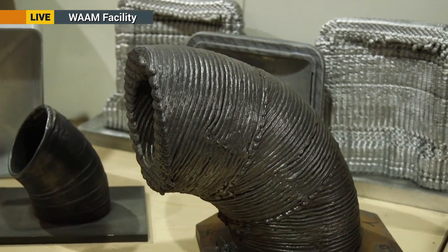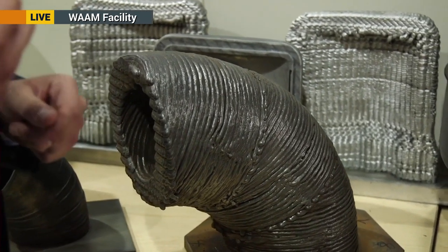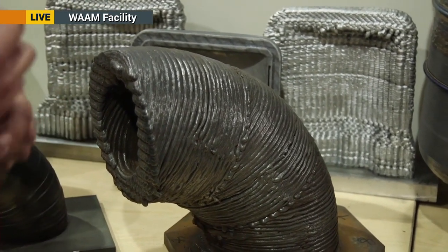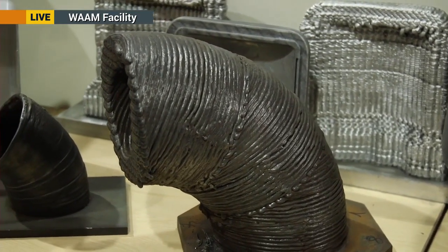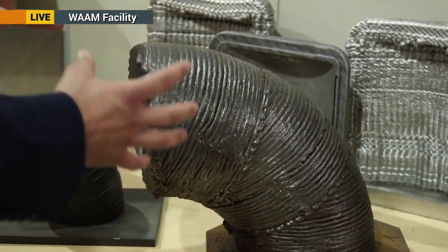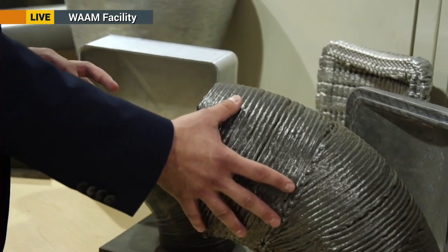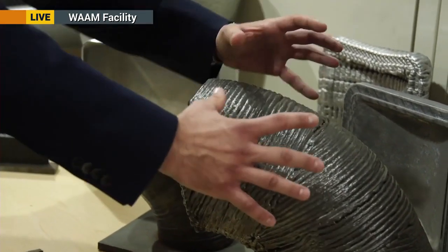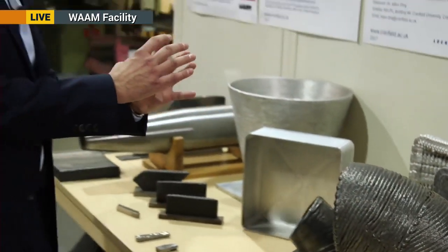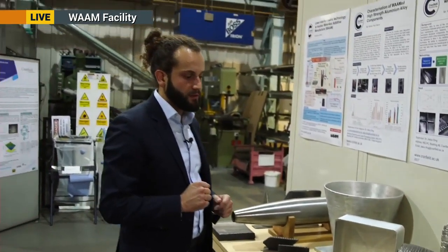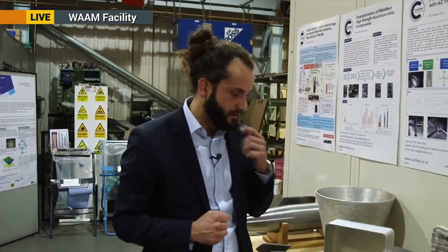The idea is that if the designer gave us the final shape, the final optimized design of the entire flow loop, this component would be no longer made out of several 90-degree bends, which are then joined together to straight bits to take the fluid from A to B, but we could have a nice elongated component which minimizes the pressure losses in the duct itself.